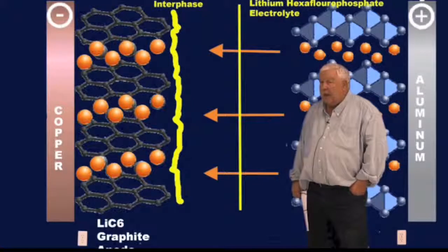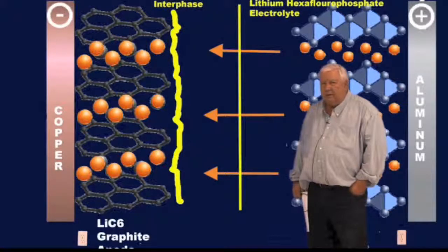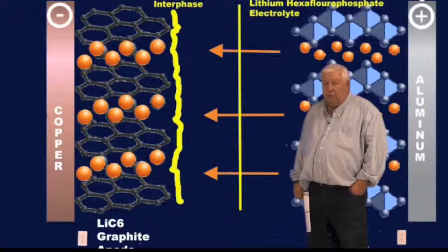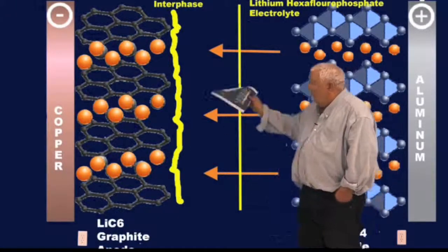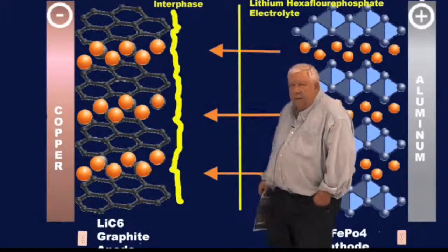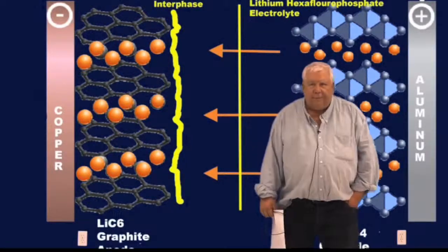And you can send a battery into thermal runaway with external temperatures, but it has to be up 70 degrees centigrade. So we look at anything external to the battery above 60 degrees centigrade, 158 degrees Fahrenheit, as being bad news. As long as you're below 158 degrees Fahrenheit on your anode or on your case or so forth, you're probably not doing grave harm to the batteries.